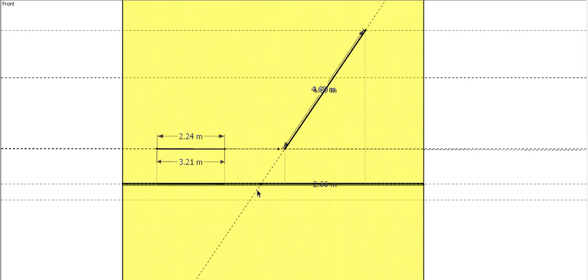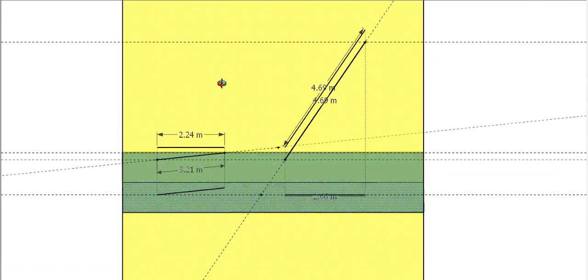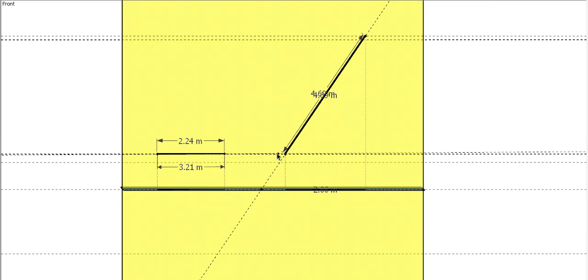Okay, and that will be our front view. Just to clarify again, in the case of this line, this is the vertical trace, and vertical trace can be seen only in the front view. We are looking from the front and see this point here. This is our front view of the line, and we can see the vertical trace at this particular point. We will name it VT in the front view itself, capital V and capital T. This is the vertical trace.